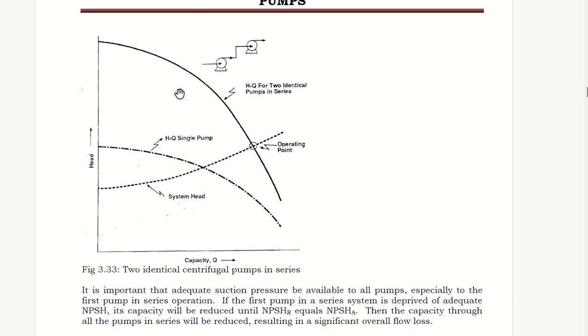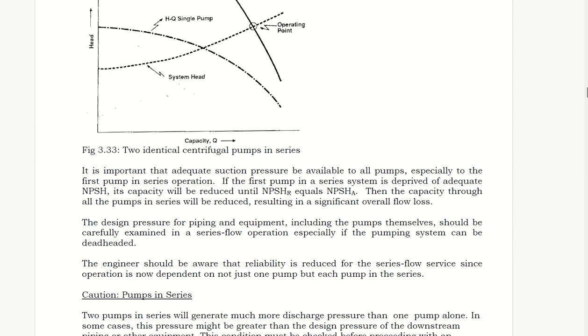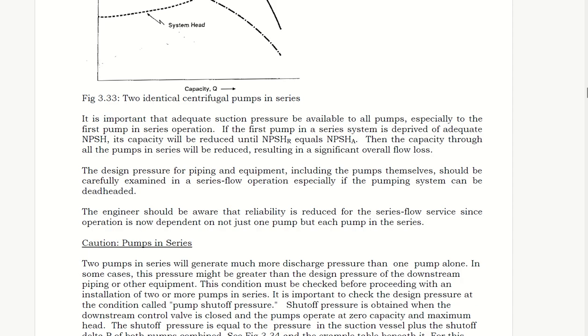Again, guys, you can see this is the single pump operation, and this is the two identical pumps working in series. Actually, you can see this raised head, and some more lines we will study. It's important that adequate suction pressure is available for all the pumps, especially for the first pump in series operation.